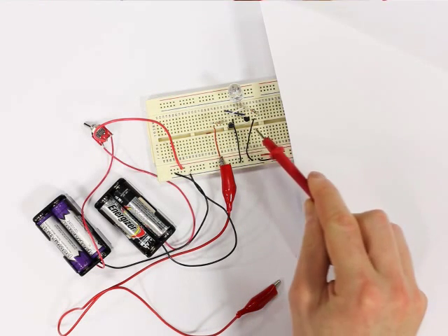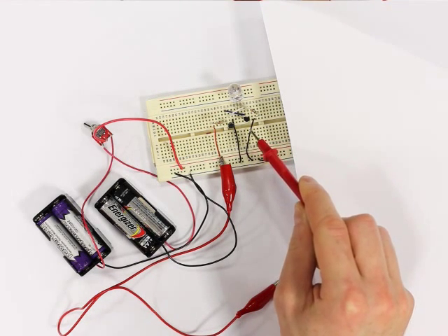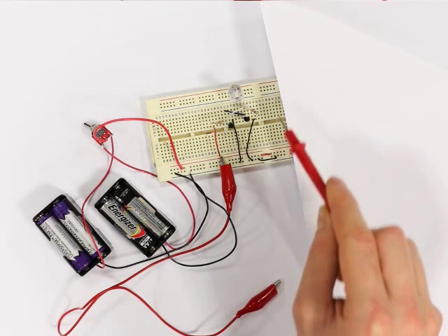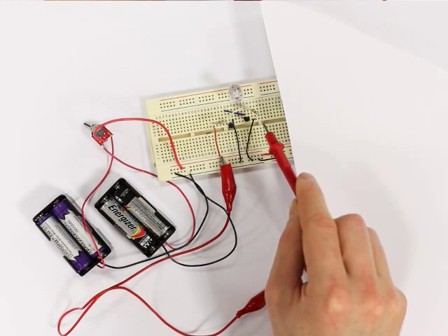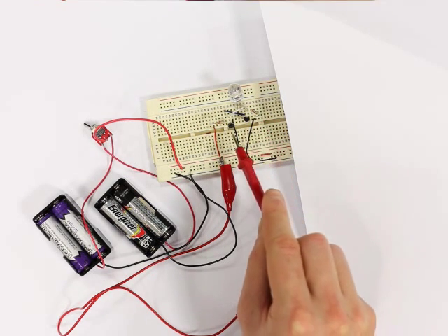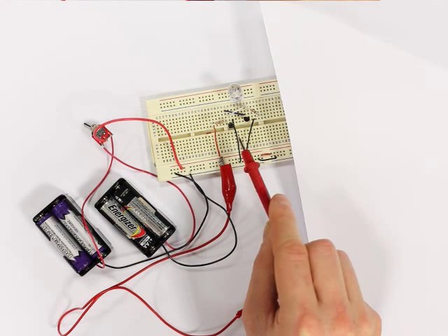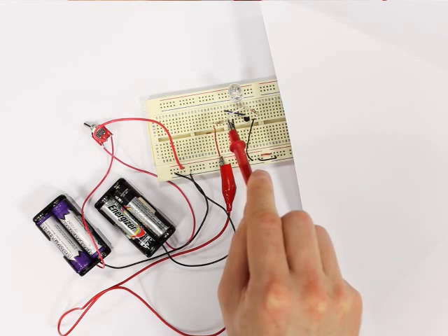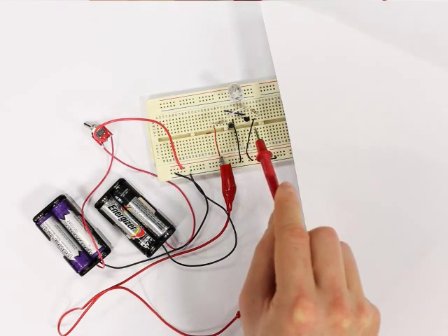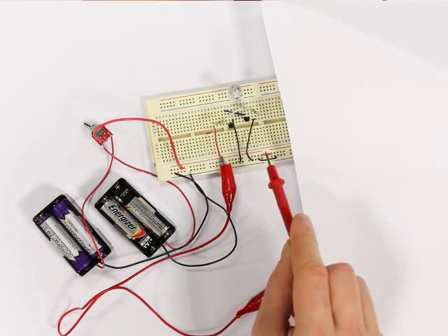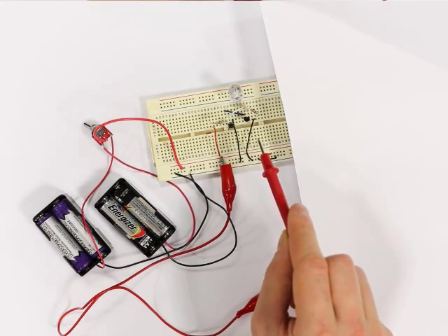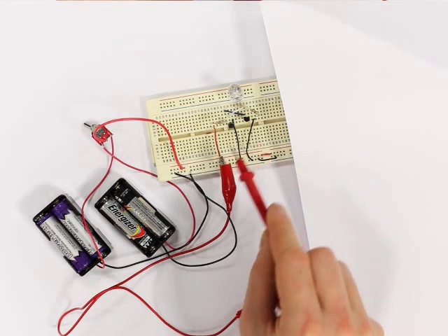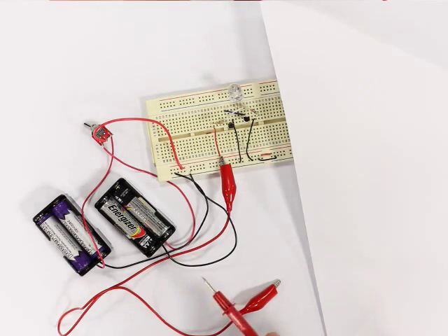As for the components, here is my MOSFET connected between the LED and the sense resistor. And then this one here is the BJT, which is connected to the gate resistor, and that blue wire there connects both of those to the gate of the MOSFET. Now it's probably not immediately obvious which pin is which on the MOSFET and BJT, but the data sheets will tell you that.